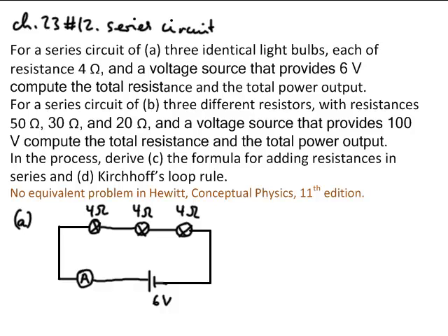And then it also says that the voltage drop across each device is proportional to its resistance. Ohm's law applies separately to each device, and so that means that the voltage drop on each one of these here is equivalent to each resistance. That's also why it shows equal resistances across here, so each one of them is 4 ohms. There are 3 of them, so they have to share the voltage, so each one of them gets 2 volts of that voltage drop of 2 volts.